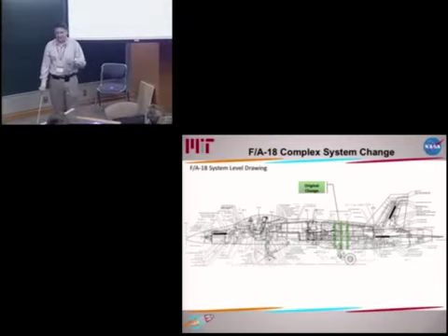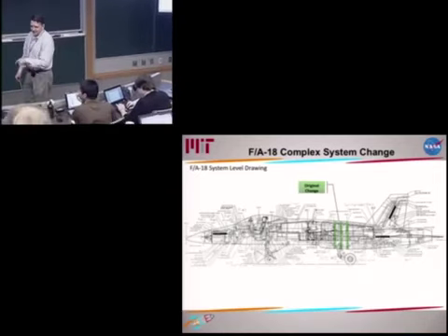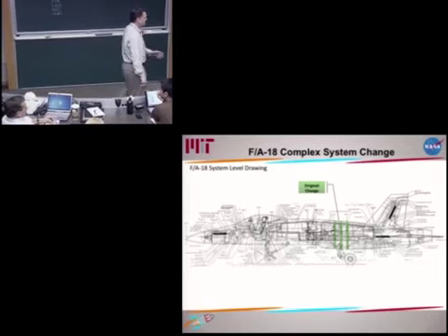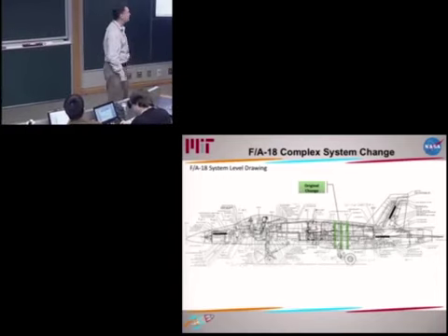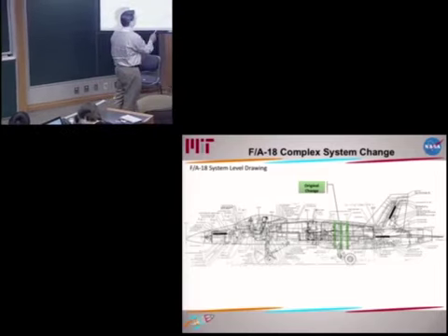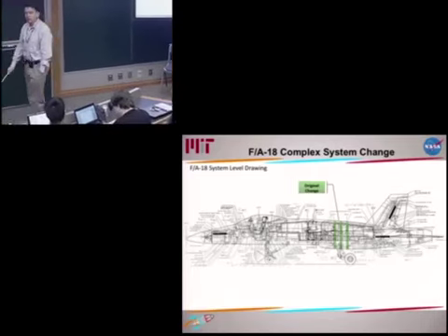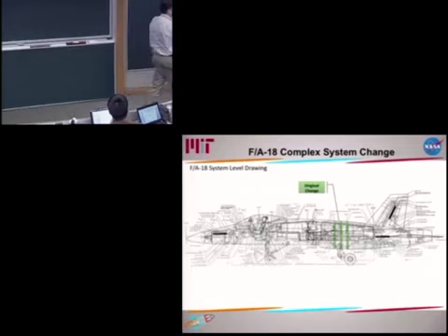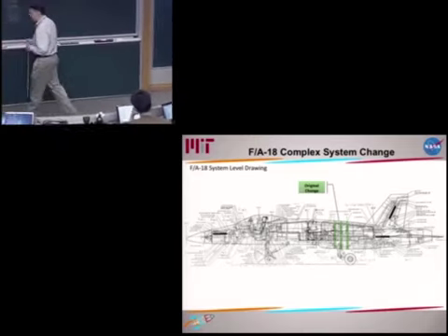And you remember last night we talked about, when Jeff was talking about the superconducting magnets, and we found out it's a titanium alloy. Titanium is a great material. It has great thermal properties. It has great fatigue properties. It doesn't propagate cracks very easily. The problem is it's expensive and it's heavier. It's much heavier. It has a density of about 4,400 kilograms per cubic meter versus aluminum, which is about 2,700. But we did decide to make that change. We made some other changes as well to get the aircraft's fatigue life to where it needed to be.